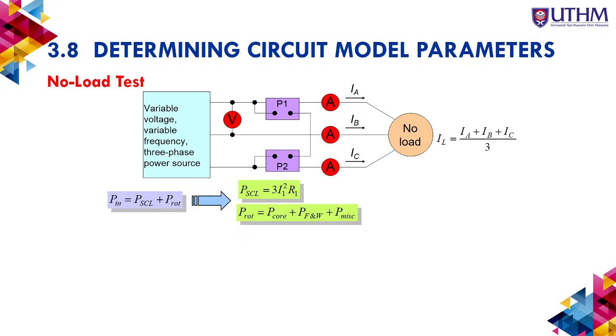For the no load test, the no load test of an induction motor measures the rotational losses of the motor and provides information about its magnetizing current. So this is an important keyword. The test circuit of this test is shown in the figure.